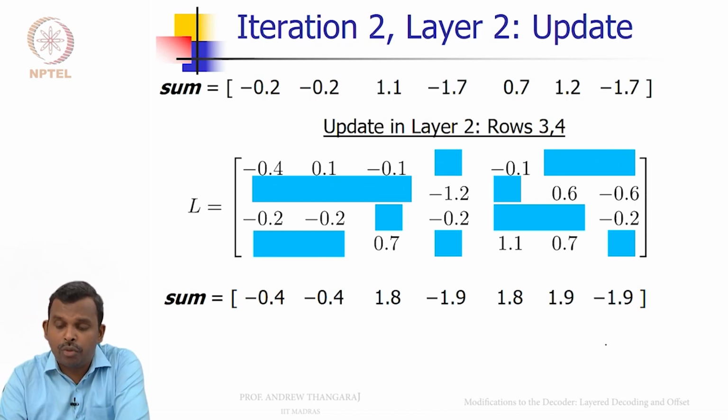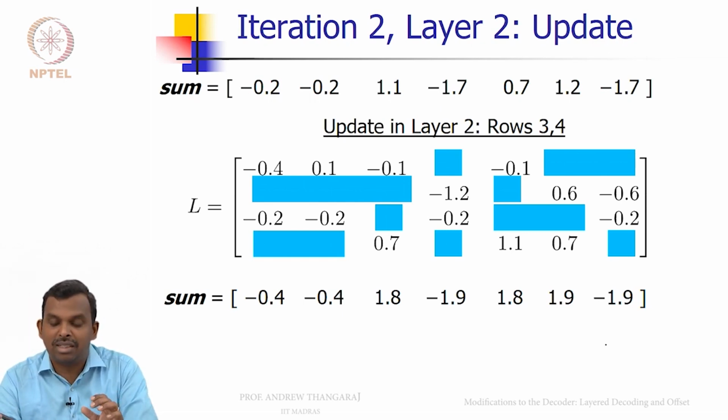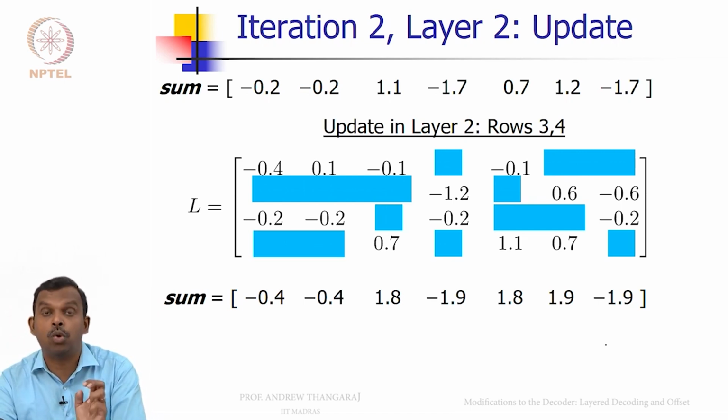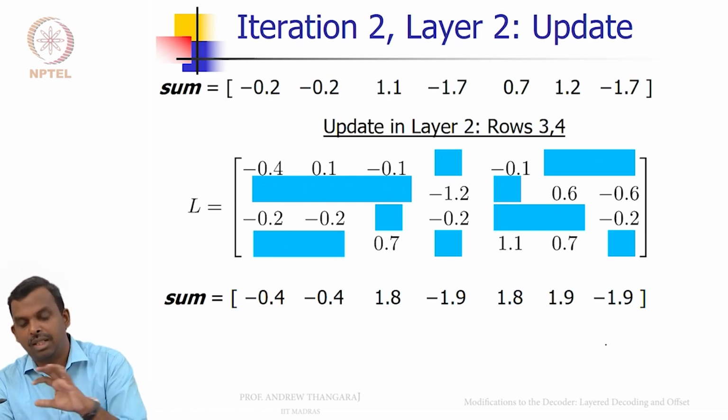Now if you look at this structure of the storage, this is a very small storage, so you don't have major challenges when you implement. But how to store this efficiently, how to read from this efficiently, how to write back into it efficiently, how to do that in parallel is the biggest challenge when you implement LDPC decoding. And today there are really very advanced IP cores available from many people. They've really optimized this storage very well, and can run at multiple gigabits per second. It's easy to get implementations like that today. So it's not a very difficult operation, but that's how it happens.